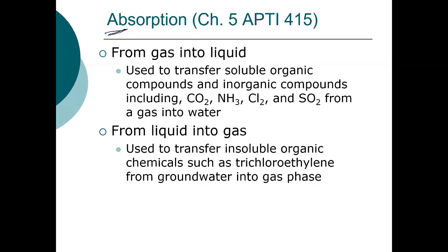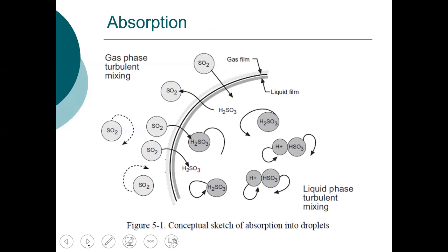Or we can transfer a chemical from a liquid into the gas. So for instance, if we have groundwater that's contaminated with trichloroethylene, tetrachloroethylene, we can then transfer that chemical from the groundwater into the gas phase, and then we can subsequently treat it in the gas phase. So what we're looking at here is a mass transfer process.